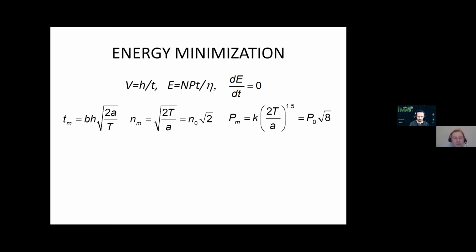optimal lift. Also, what about the velocity of optimal lift? If we introduce the velocity of the air stream past the propellers, which we can measure rather simply, then the optimal velocity of climb is about this value of stream velocity past the propeller. So also we can obtain practically without any calculations this optimal velocity of climb by measuring the velocity of the stream.